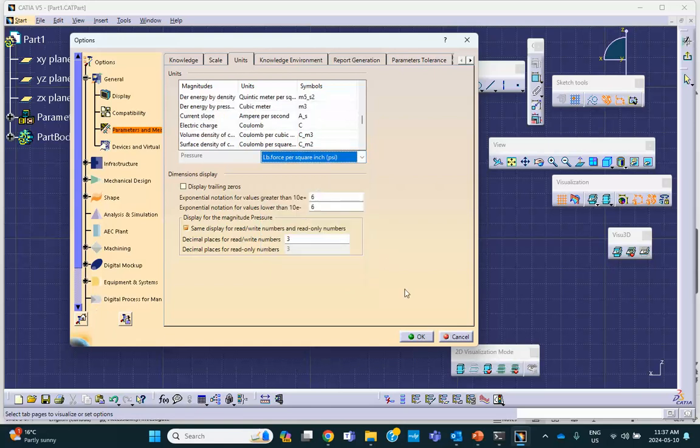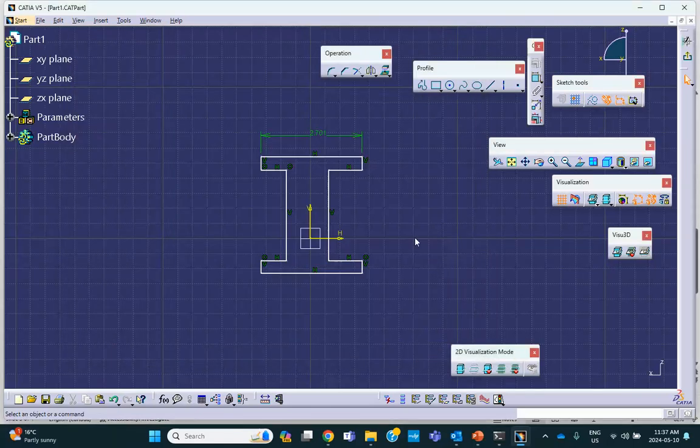Okay, good. Now, this is right now 2 inches. So the drawing that I showed you shows that that is actually 1 inch, and this is 0.25. So let me dimension these first. Actually, before I do that, let me make this thing nice and symmetric with respect to that line.